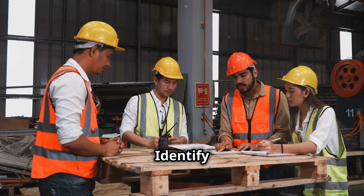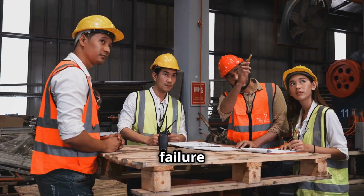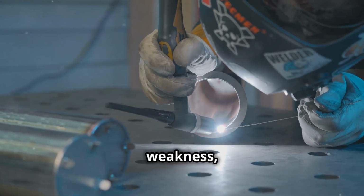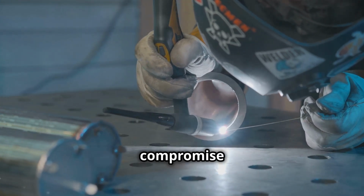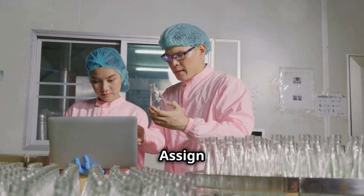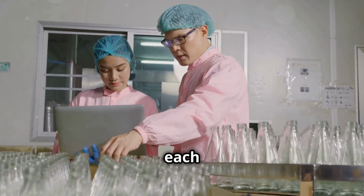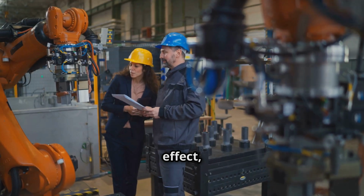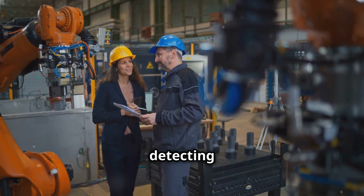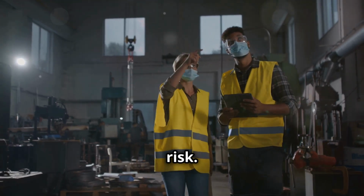Step 3. Identify the effects of failure. Analyze the potential effects of each failure mode. If the weld fails, the result might be structural weakness, which could compromise the safety of the final product. Step 4. Assign severity, occurrence, and detection ratings. For each failure mode, rate the severity of its effect, the likelihood of it occurring, and the likelihood of detecting the failure before it reaches the customer. This helps quantify the risk.